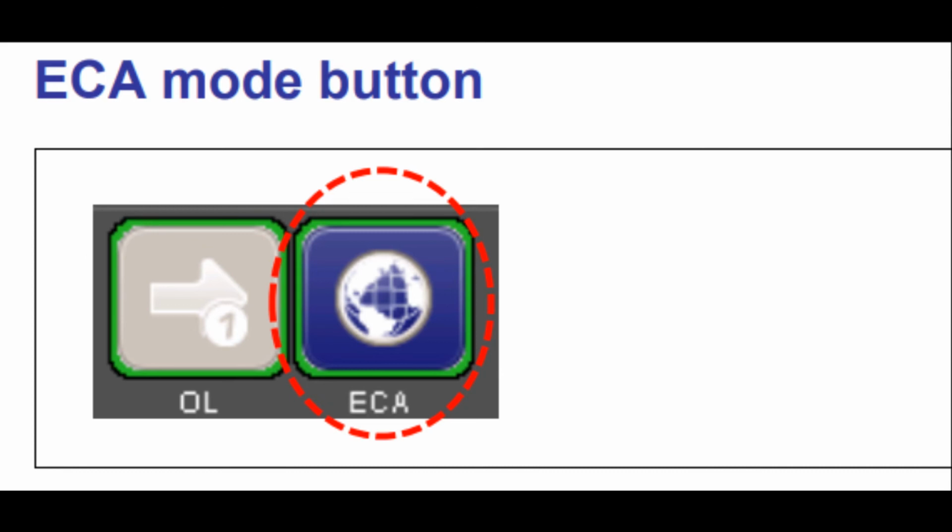ECA mode is set to on. The water control settings and SOx CO2 ratio limit for ECA mode are used. A green border shows around the ECA button. A green message bar on all HMI screens shows that ECA mode is activated. When the ECA mode is set to off, the water control settings and SOx CO2 ratio limit for global mode are used. A green message bar on all HMI screens shows that ECA mode is activated.